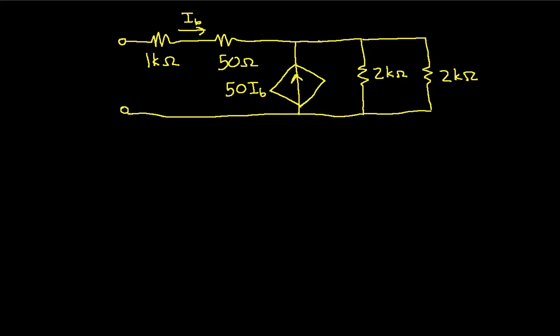We'll bring up a picture of just the small signal model, and what I want to do then is add a test source. In fact, here we'll do this in a bright red color. So I add a 1 volt test source, and then what I need to figure out is the current that goes into the circuit as a consequence of this 1 volt source.